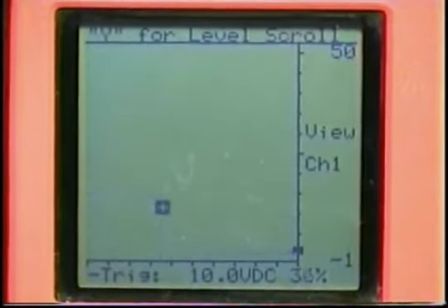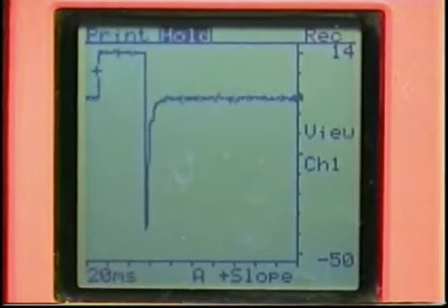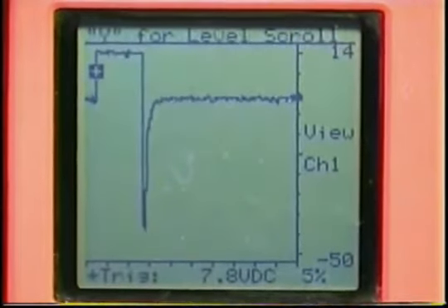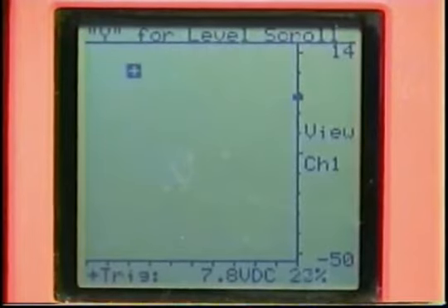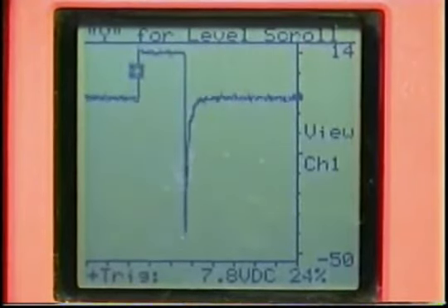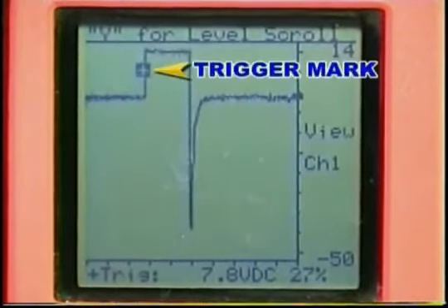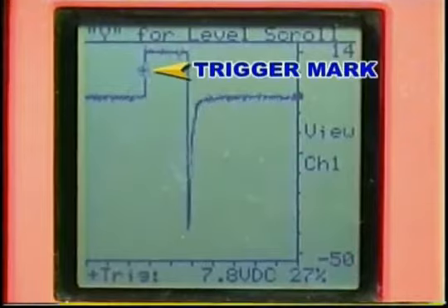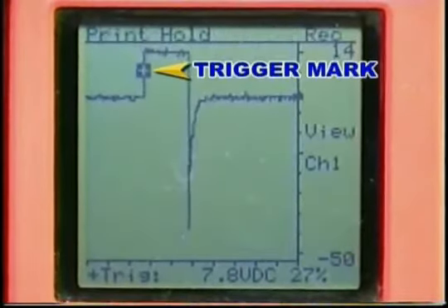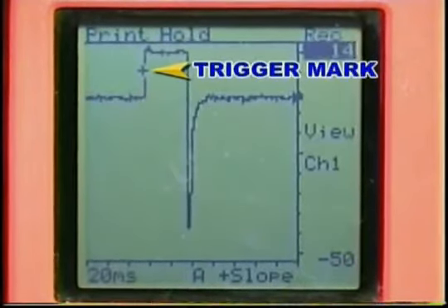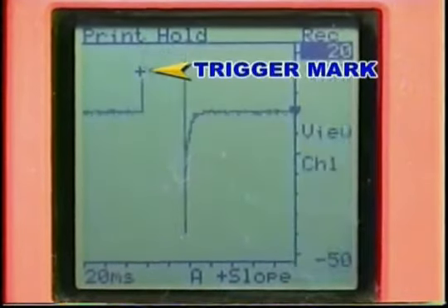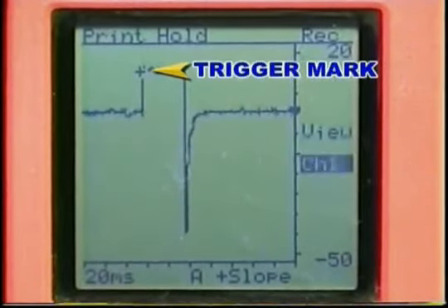As soon as we get set up, we go to the ground control circuit. And then, we plot the waveform on screen. By centering the trigger level or the small x, you can clearly see the injector waveform now on screen. This is a lot easier than actually plotting numbers using a digital multimeter. Following, we see the trigger mark and the injector waveform inverted. Then, we see the injector open time, which is the space between the two vertical lines.